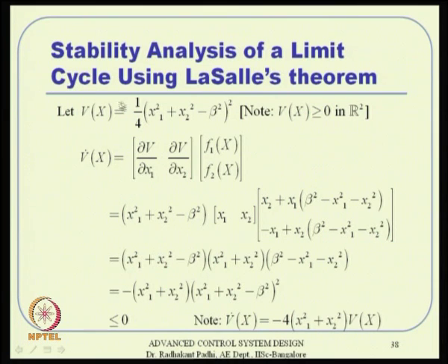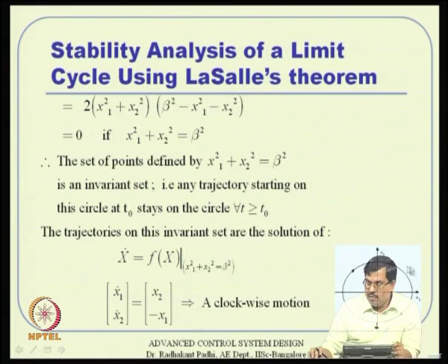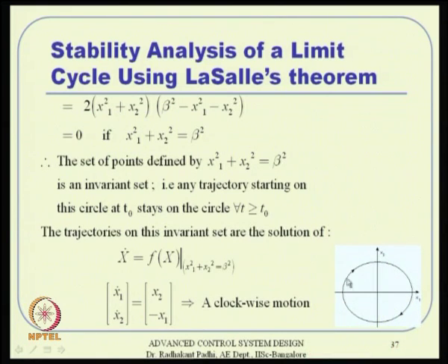Having said that, it turns out that it is convenient to work with Lyapunov functions also. So, in this particular example you can think of it as a Lyapunov function candidate around the local neighborhood of the limit cycle. Because this particular expression, if it is non-zero, gives us some sort of a distance measure from the limit cycle. If it is 0, we are moving on the limit cycle. If it is non-zero, we are moving away either inwards or outwards, either way. So, this actually gives us some sort of a distance measure quantity.